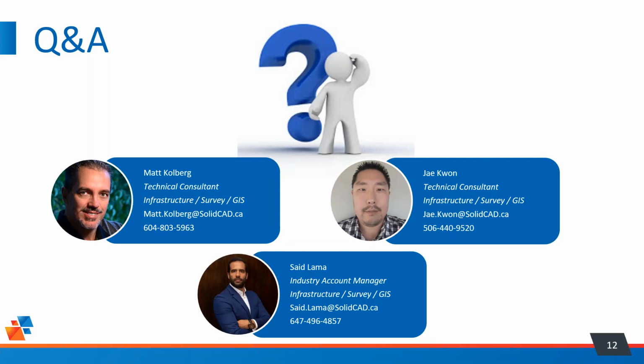Agreed. I think possibly what could happen is your ultimate goal is to deref the pipe network in, so you do so, but you want to xref the same drawing because maybe there's other stuff in there. You don't want to deref, you want to xref instead. So maybe due to happenstance, they just happen to be xrefed in there. So what I would probably do in that case is just turn off the xref layers for the pipes if they're already being derefed. But you're right, basically pick one. And if you can't pick one, maybe turning off the layers is the best idea.